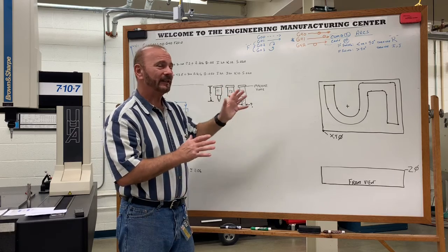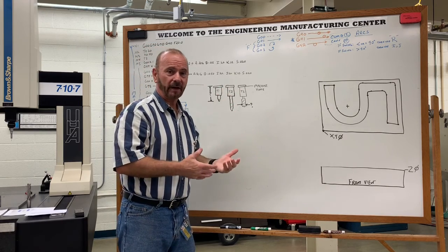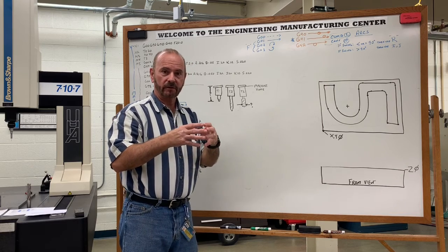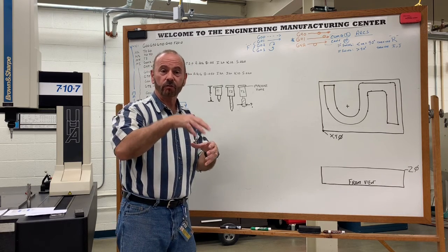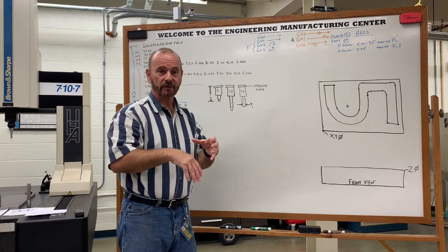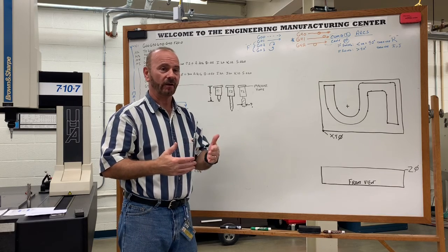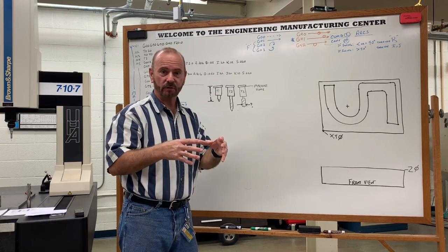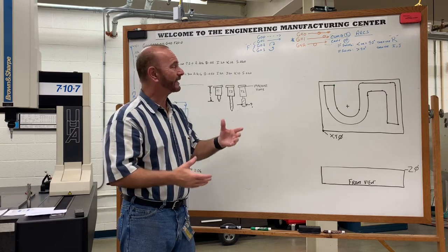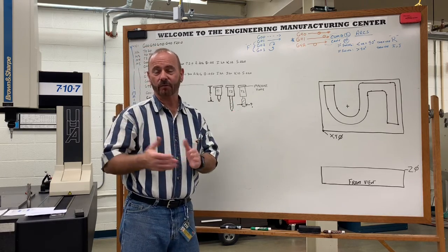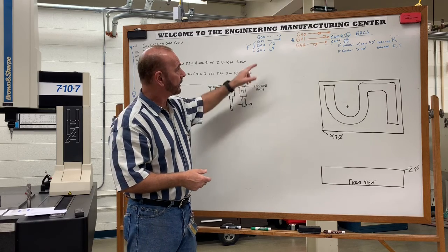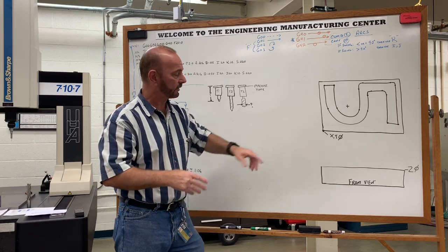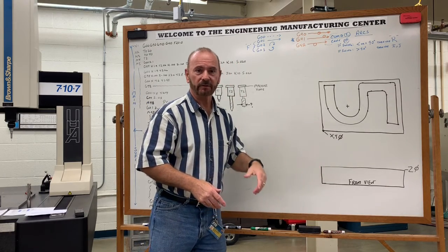So let's liken this to SolidWorks or AutoCAD that you're used to using. What do you use those to make your extrusions and your cuts? You typically take lines and you take arcs and you trim them together to make some type of a shape, and then that becomes your cutting extrusion tool. Well, it's the same thing here, except in this realm of subtractive manufacturing, we combine these lines and arcs, and then we use the Z depth of the cutter to push the cutter into the material to cut the depth that we desire.